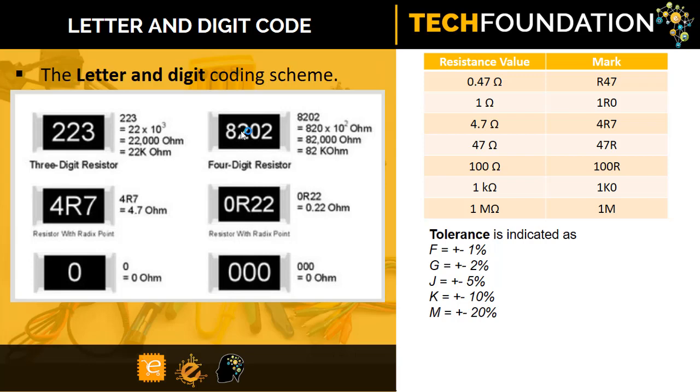Now when choosing a resistor, you will have to know its wattage too. The way you do that is by calculating how much voltage is expected to drop across it and the current that will flow through it. By using the formula P equals IV, you can calculate the wattage. Usually, what you do is you choose at least twice the wattage needed.